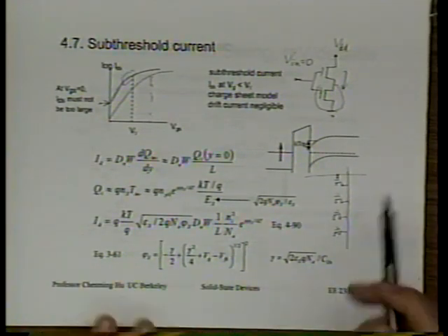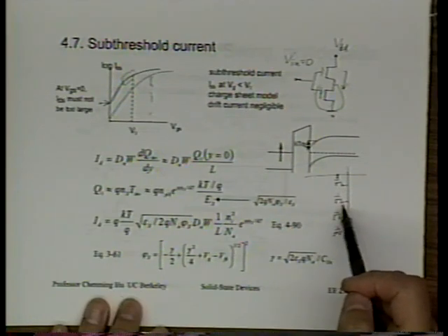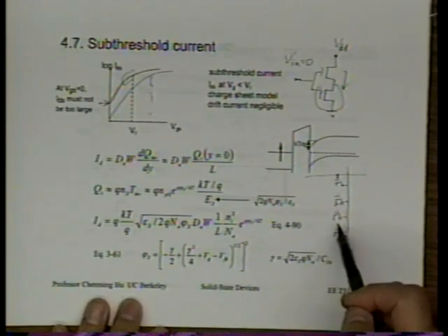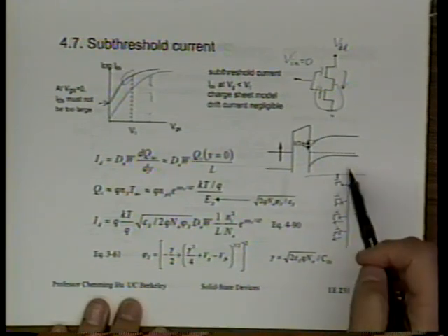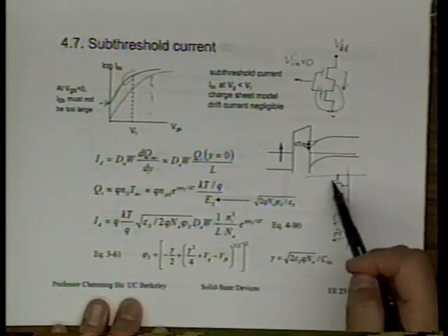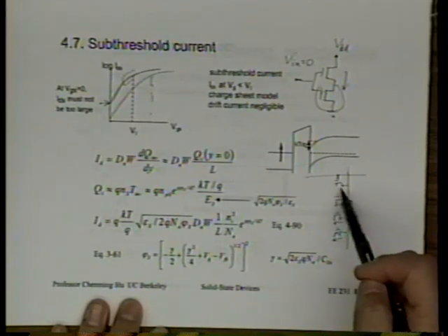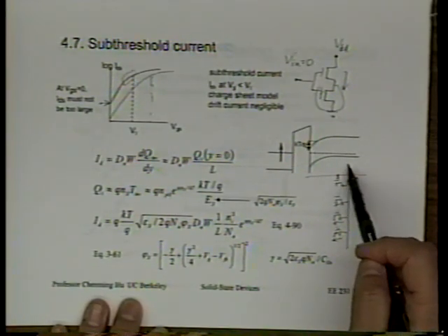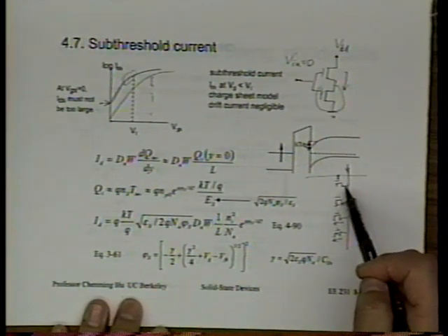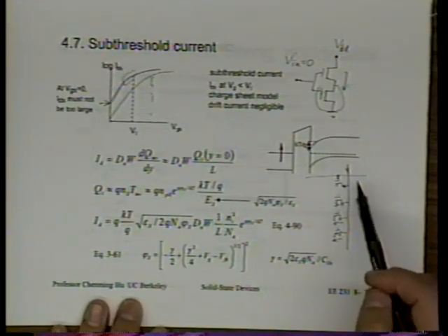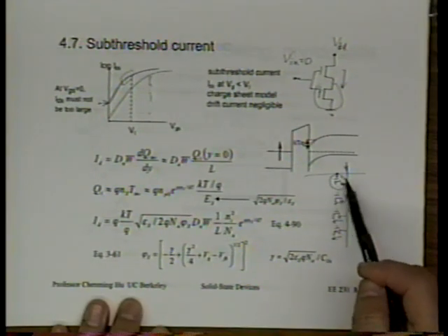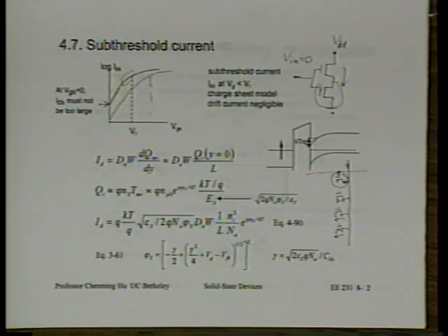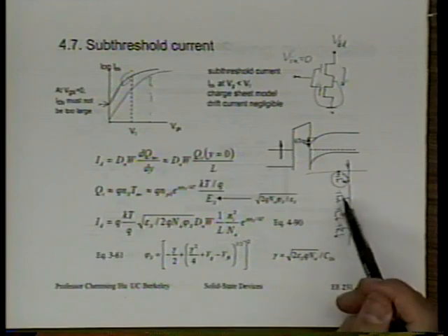And we are counting on the fact that these transistors or memory cells in the off state do not draw a lot of current. If they don't draw a lot of current, then we can just sense the 1 or 0 state of the cell that we have selected by looking at the current going through the bit line, whether we have significant current going through it or not. If we have a lot of current going through, then we know this memory is storing a bit that's on, right? If there's not much current, that's off. You can see that the read operation will not work if each of these transistors, which are not selected and supposed to be off, each conducts significant current.